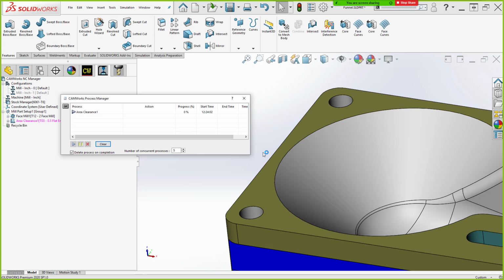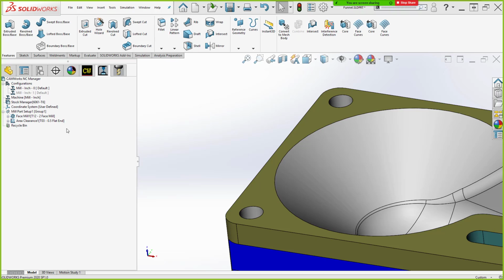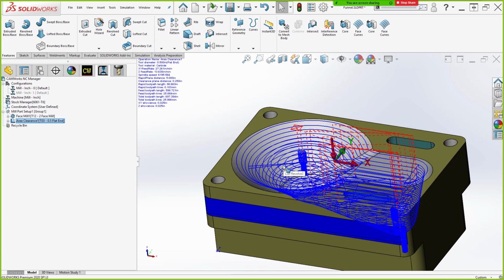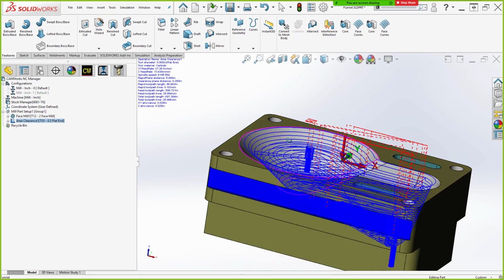So watch how much quicker the toolpath generates this time, because I don't have to analyze everything that's been done already, right? At most, it takes half the time to generate the toolpath compared to before. And it's contained in XY to that area.